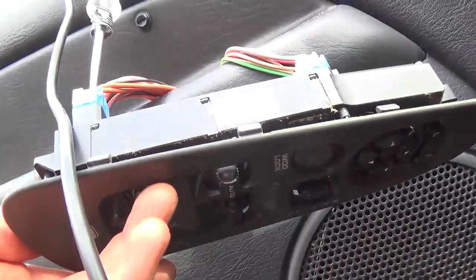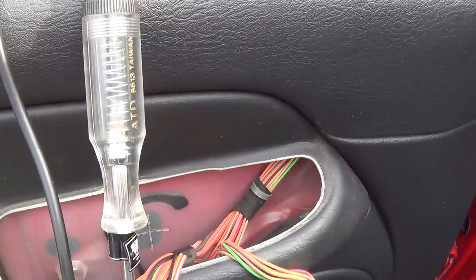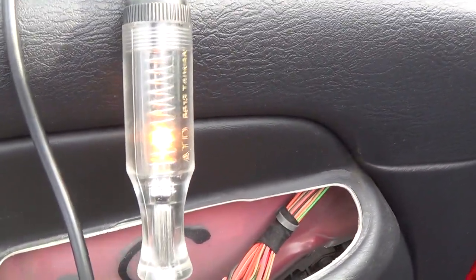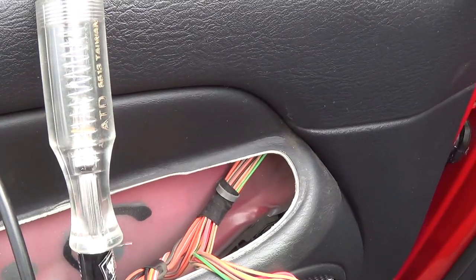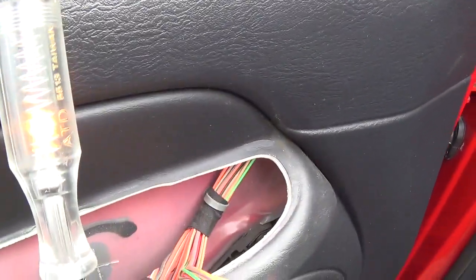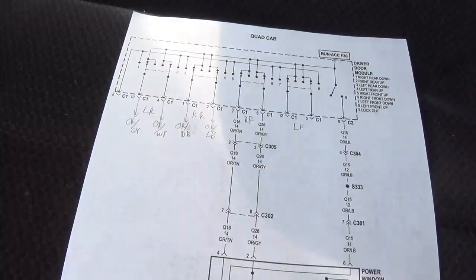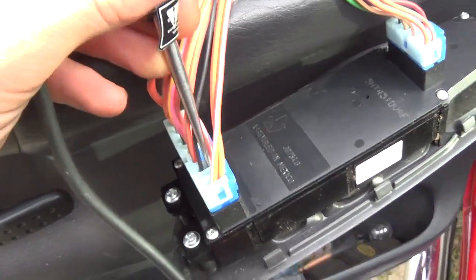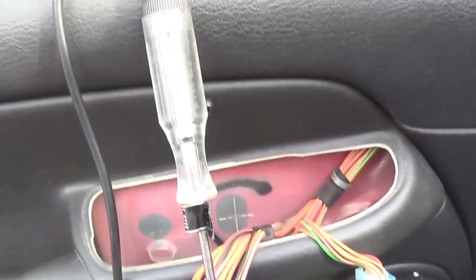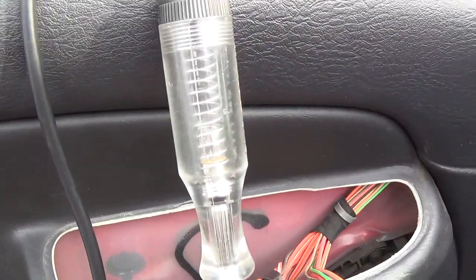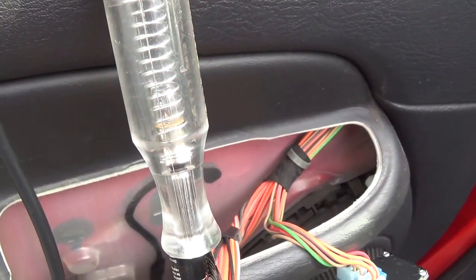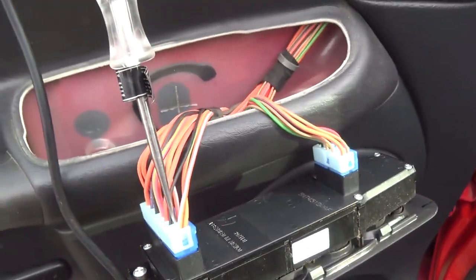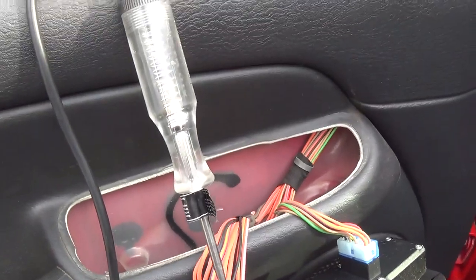Now I'm going to flip the left rear switch. So this is down. Okay, we have a test light, and up, nothing. And then the other wire should do the opposite. The orange and white. Let's see here. I'm guessing it's that guy. Yep. Lights.